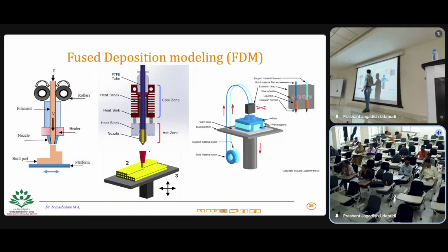Somewhere at the tip of the nozzle, your material will start to accumulate, and it is mostly exposed to the environment, which creates another problem. That's why you need to clear it regularly, so that you keep the nozzle area clean and can fuse the material.